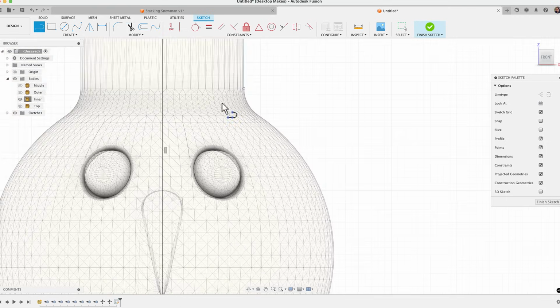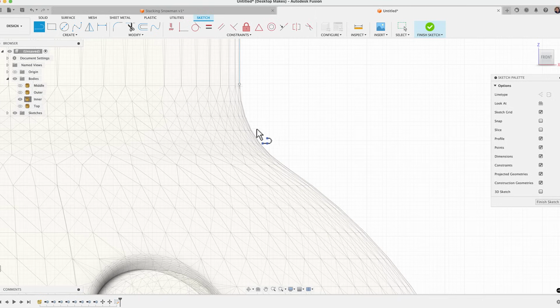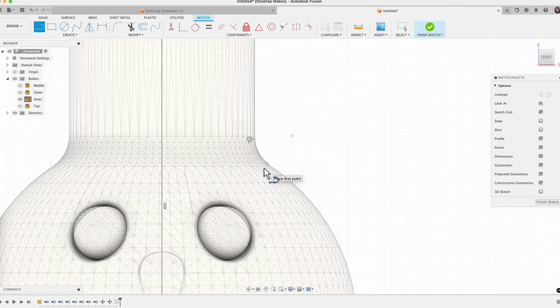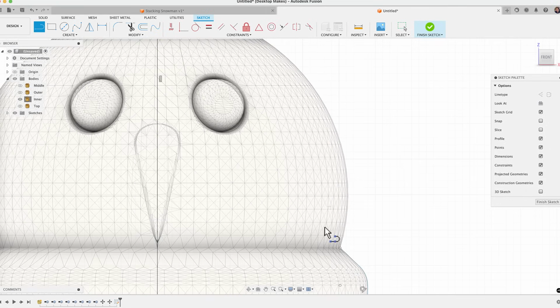Next, you know what, we'll do the same thing here. We're gonna create an arc right here. So left click to continue this line, and instead of left clicking again, I'm left clicking and holding to transition right to an arc. Hit that check mark there. And I'm gonna connect these 2 points here.